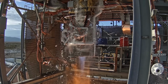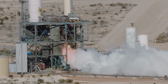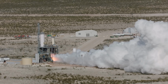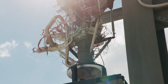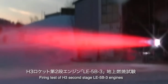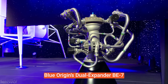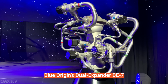This can help overcome the limitations of thrust, since you can use more of the limited pressure and heat available to power the pumps. So it trades a little bit of efficiency for the potential of increased thrust and decreased complexity. There aren't a lot of examples of the expander bleed cycle other than the BE-3U that will power the upper stage of Blue Origin's upcoming New Glenn rocket, and the LE-5A and LE-5B on Japan's H1, H2, and their upcoming H3 rockets. There's also another version of the expander cycle called the dual expander cycle that utilizes both the fuel and oxidizer, assuming that both those propellants are used regeneratively to cool the chamber.